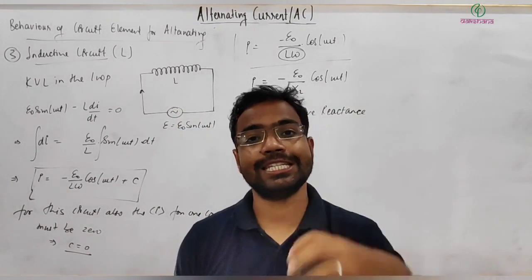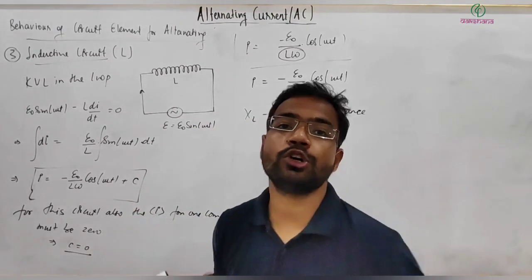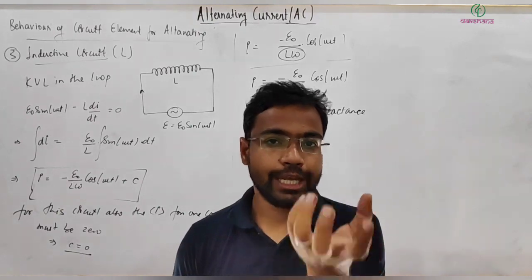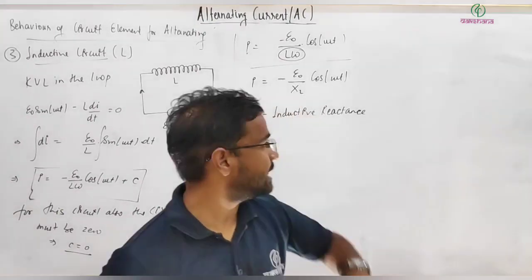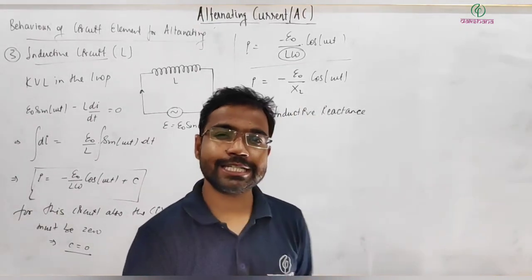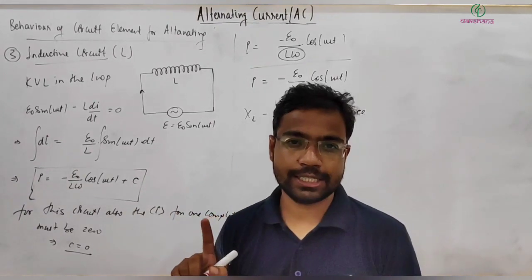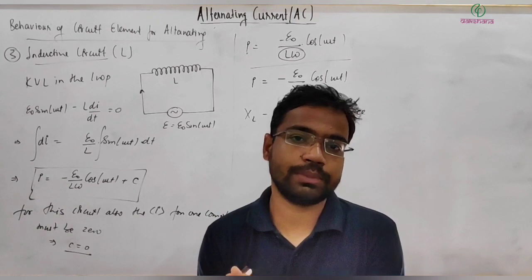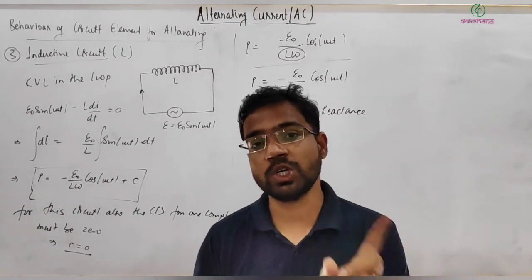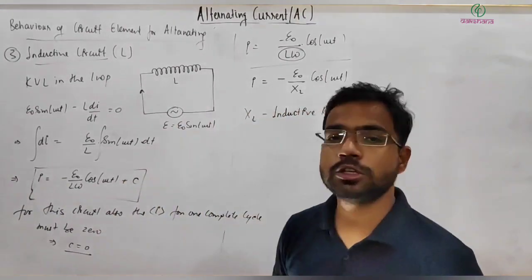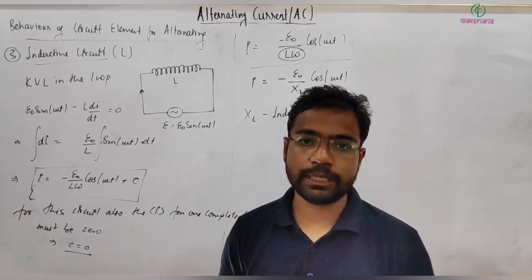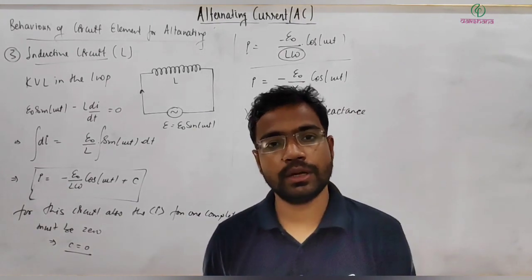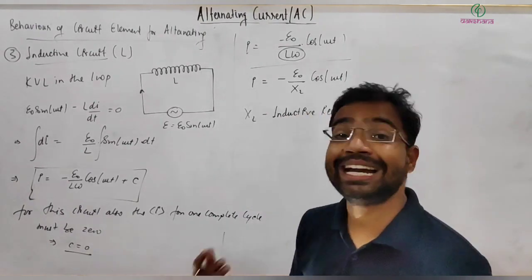So it will offer some opposition, and we measure that opposition. It's different from resistance. It offers opposition, but it's not equal to resistance, because there is no loss of energy, loss of power here, but it still offers some opposition. So we define a new quantity, and we call it reactance.